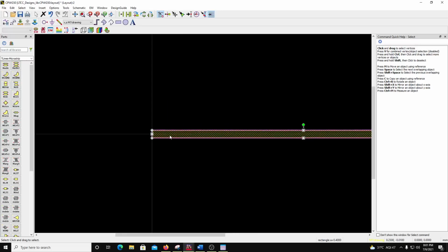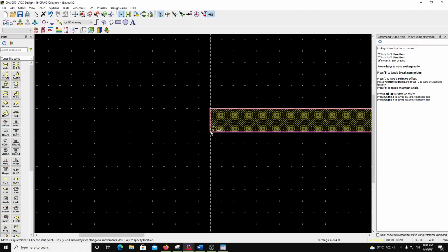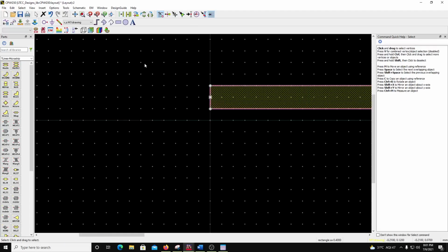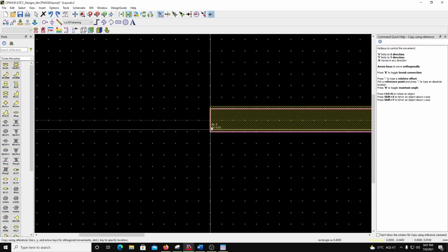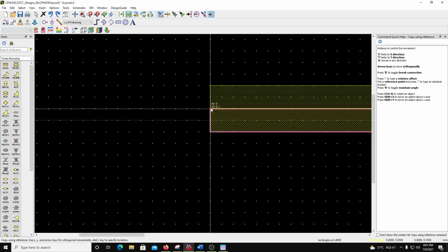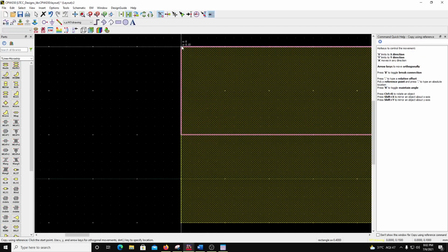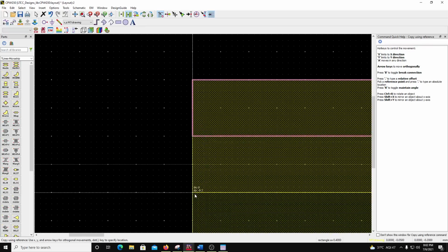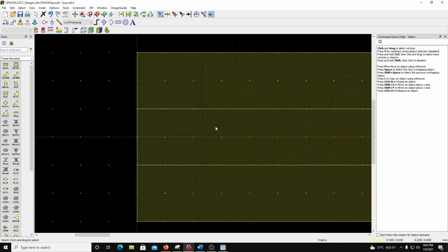Now what I'm going to do is I'm going to just copy this. So snap to the corner. So I have to snap by the corner. So I will make a copy of that. Okay, I moved it by mistake. So that's a copy. Okay, so I made a copy and I placed it with this corner. So snap to corner is enabled. So I'm grabbing the line by the corner. You see, I'm making a copy, so I'm grabbing the line by the corner and it is snapping to this corner, right? So you see that this is done, right?